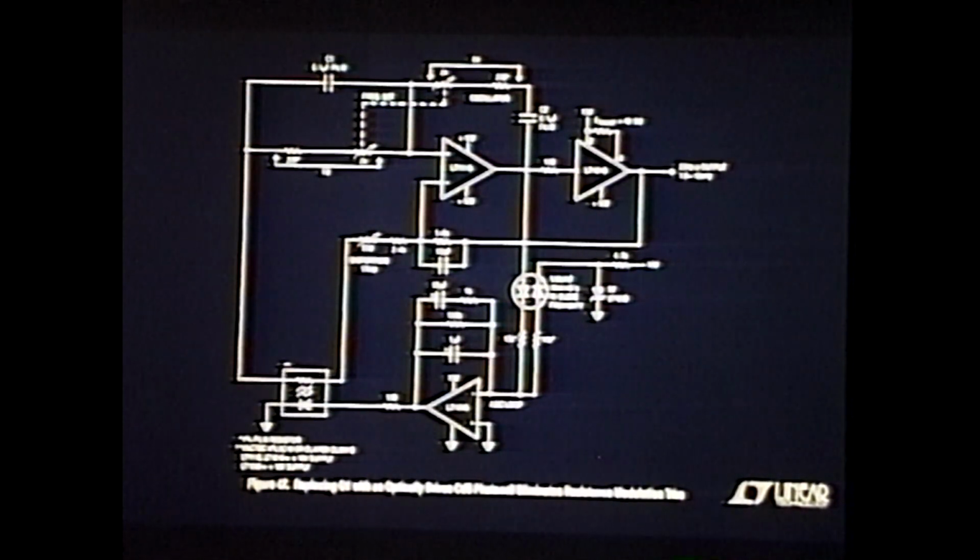One, just because I was rebuilding the circuit, I decided if we're going for the lowest distortion, one thing I want to do is unload the oscillator amplifier to give it all the open loop gain it can have. So I basically just added a monolithic output buffer here, a power buffer. Not so much to get power out of the circuit as so this amplifier sees just no load at all. I'm trying to get all the open loop gain out of that thing I can. That's the sole purpose for doing this. So this is just a gain of 1 inside the loop, just to make this thing see no loading at all.